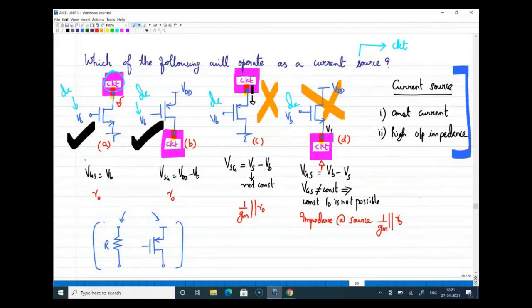In the first one, figure A, you have a transistor, which is our input transistor in the current circuit. In figure B also you have a transistor, and that is actually our load transistor. I mentioned that a circuit will be attached here. What is that circuit now? In our present circuit of CS amplifier with a current source load, the circuit I meant here is nothing but the input NMOS transistor. So coming back to Avinash's question, if I replace the PMOS with an NMOS load in this fashion, that is figure D, what will be the effect?